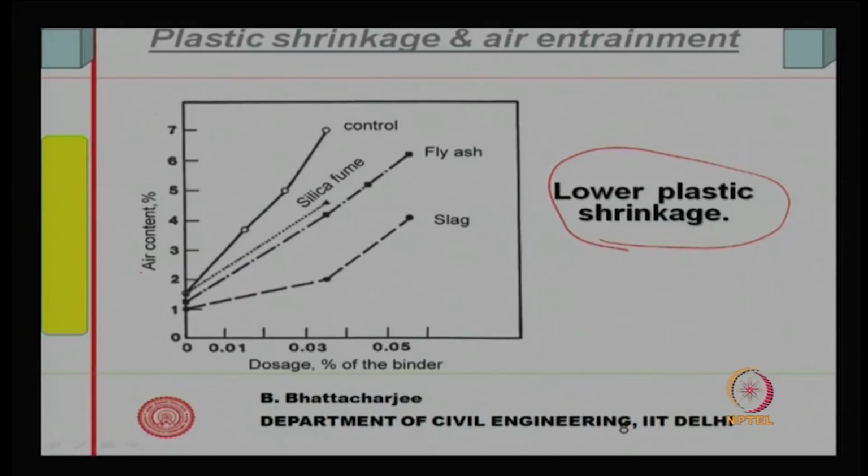Obviously, there is a reduction in air content with all the mineral admixtures. If I have increased the dosage of the binder, I find that there is a reduction in the air content, whereas control gives you much higher air content. They all reduce the efficiency of air entrainment.